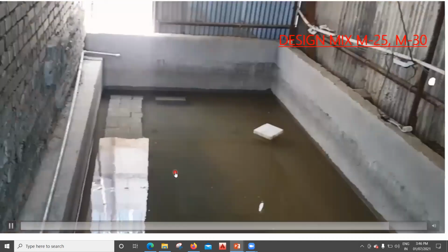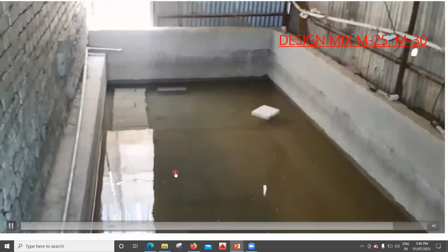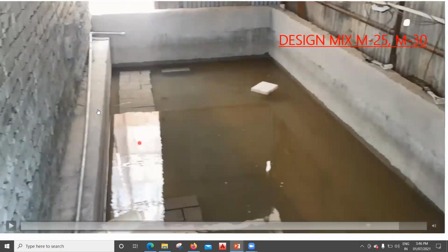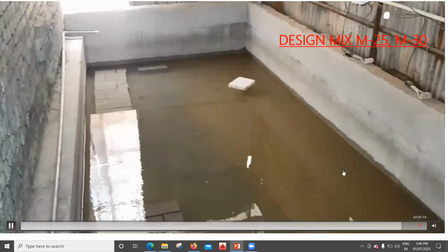So all this here, what will happen? Proper quality control is there, and we'll make sure that the concrete we have used, after doing a cube testing, achieves the same strength. Because here we try to verify the results, whereas in nominal mix we never try to do that. We assume that the strength is gained over there, right?